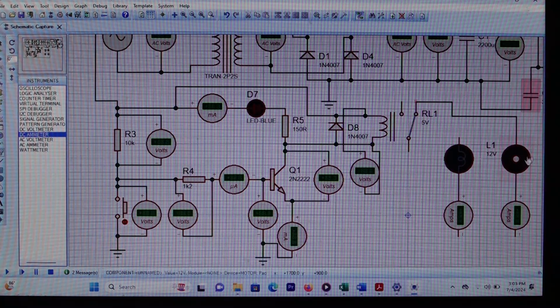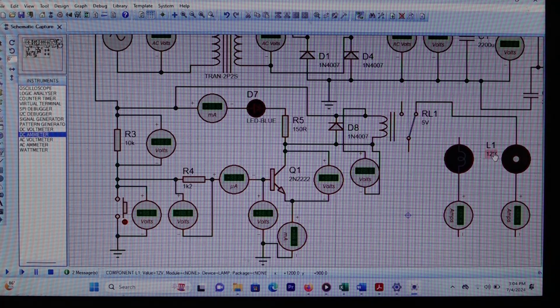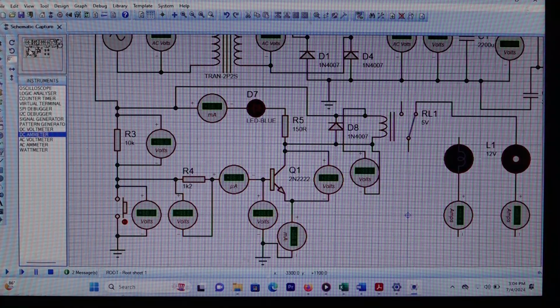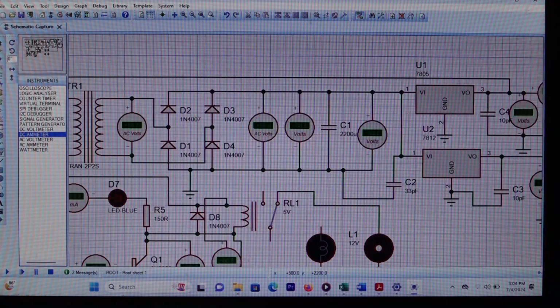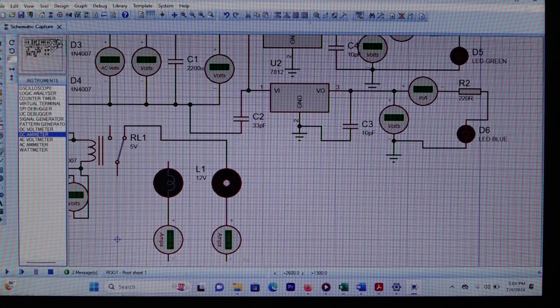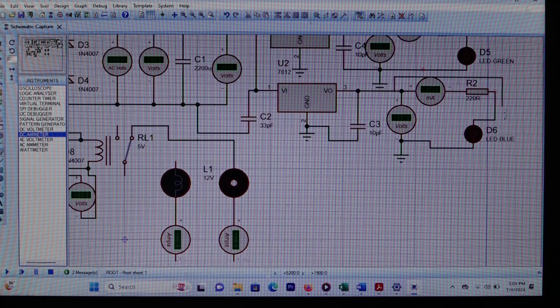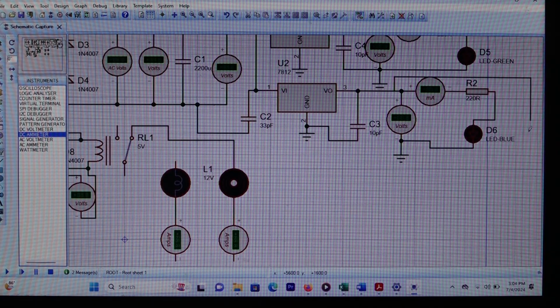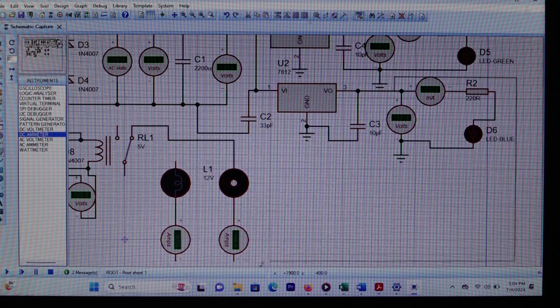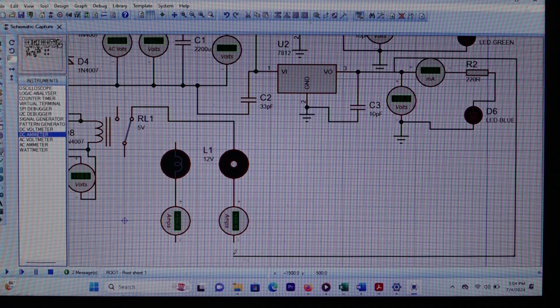And this lamp has 12 volt written on it, so it needs 12 DC voltage. The operating voltage for this lamp is 12 volt. It's not AC, it's DC. So we have to go back to the output of our 12 volt linear power supply. So this is the point. You have to take 12 volt and then we have to move and connect across what?